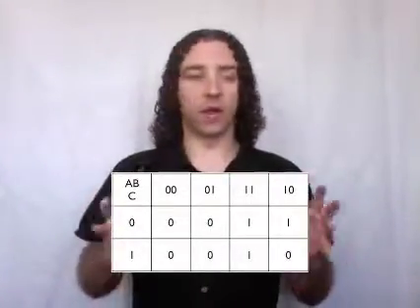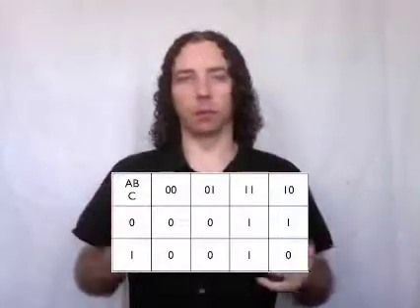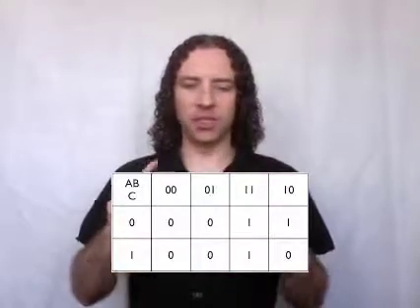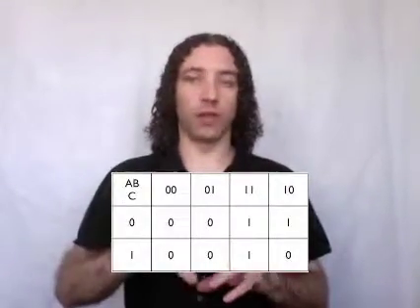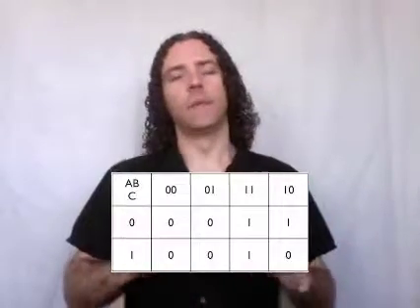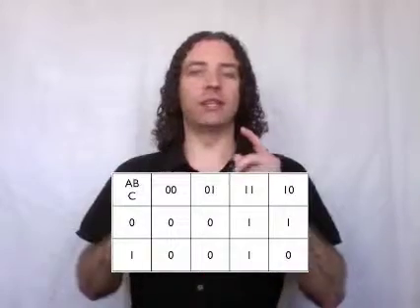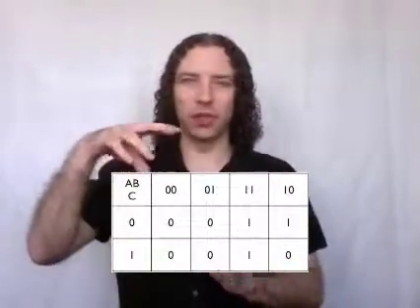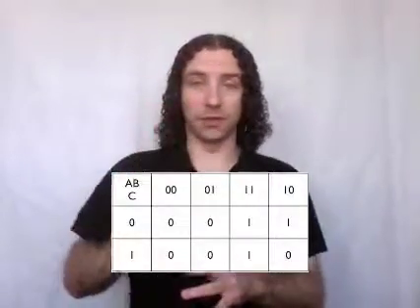And now we can see, okay, fine, there's the 3 values there as they were before. Well, now what? Well, the thing you're trying to do with a K-map is you need to identify all the groupings of 1s. You can do this with 0s as well, but in this case it makes more sense to do it from 1s. That actually make up a rectangular area which is a power of 2. Well, why a power of 2? Because a power of 2 means that you're actually grouping different variables that you're passing in as inputs together.